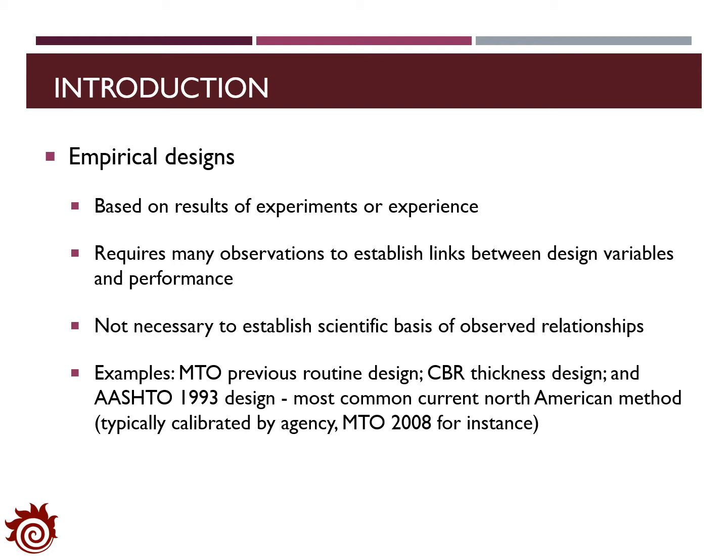There are some typical empirical design models, such as the MTO previous routine design, CBR thickness design, and the AASHTO 1993 design, which is commonly applied for North American roads. And this model is also calibrated by MTO, and the MTO 2018 method is generated based on the AASHTO 1993 design, which we will introduce in the rest of this lecture.